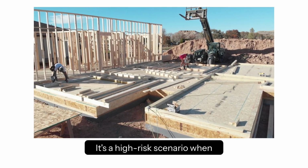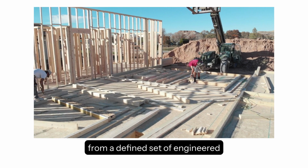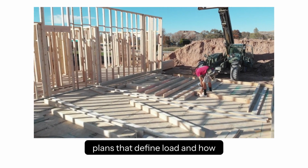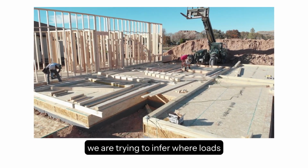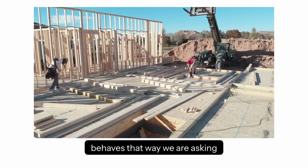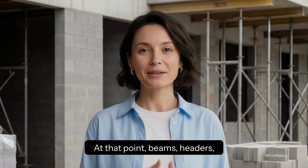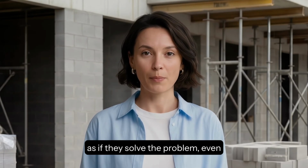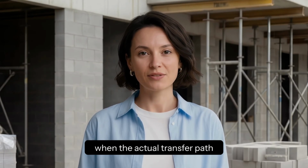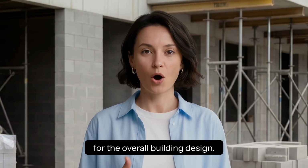It's a high-risk scenario when teams are no longer working from a defined set of engineered plans that define load and how the load is being transferred. If we are trying to infer where loads go and hoping the structure behaves that way, we are asking for problems. At that point, beams, headers, and bearing walls can be treated as if they solve the problem, even when the actual transfer path has never been properly checked.